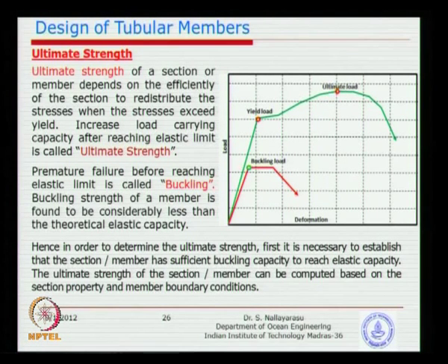So we just need to see where. If I make the column slightly bigger, I will spend more on cross section because more money needs to be spent on the material, but then I am going to use the available inherent characteristic called the material yield. Full yield is used so that I am not wasting money. So that means the proportioning of the member sizes is as important as selecting the right material.